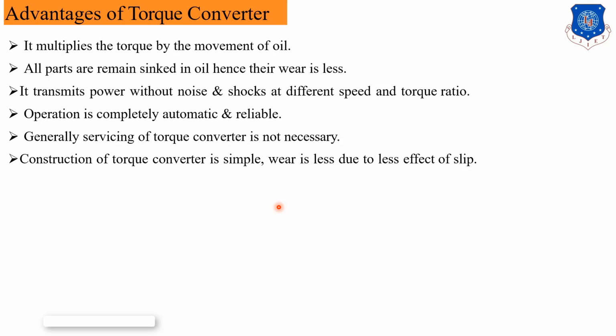Okay, and it transmits power without noise and shocks at different speeds and different torque ratios. That means power is supplied without noise, and no shocks are there. Operation is completely automatic and reliable for our vehicles. Generally, servicing of the torque converter is not necessary. Other devices sometimes need servicing, but in the torque converter no servicing is there. Construction of the torque converter is simple. Wear is less due to less effect of slip.